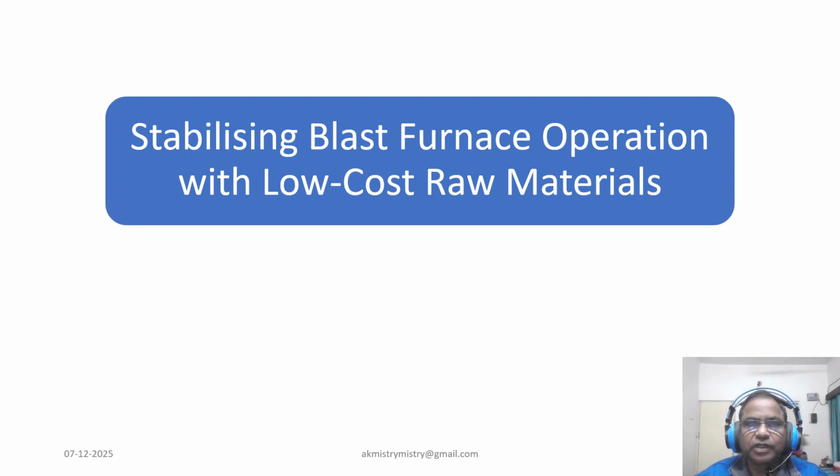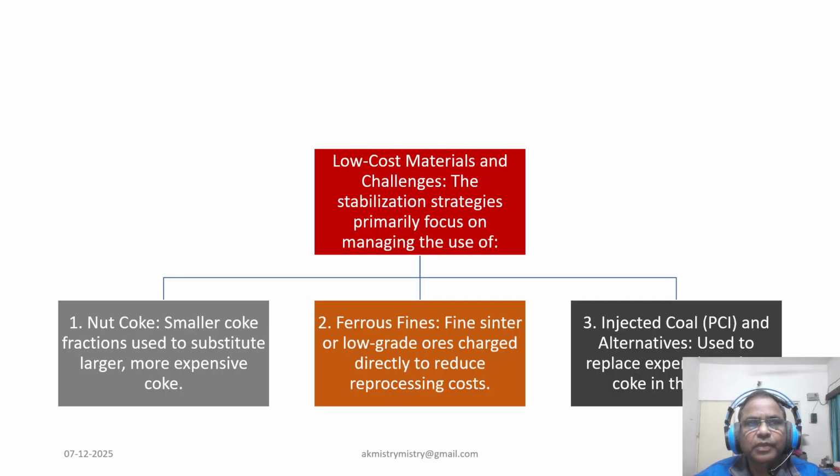The areas of intervention cover stabilization techniques, which are based on rule-based operation and operational guides. For nutcoke charging, the goal is to charge all available screened nutcoke without losing process efficiency. Assuming satisfactory coke quality, nutcoke is typically mixed within the ore layer to improve chemical reaction kinetics.